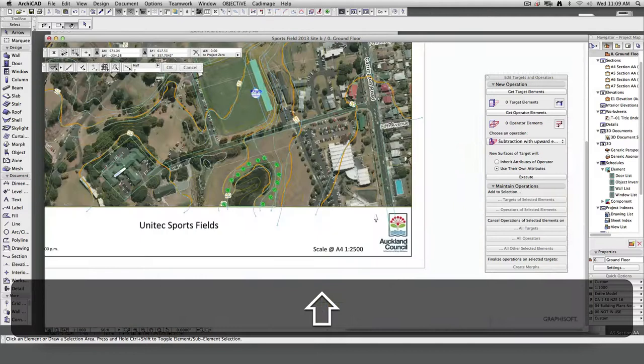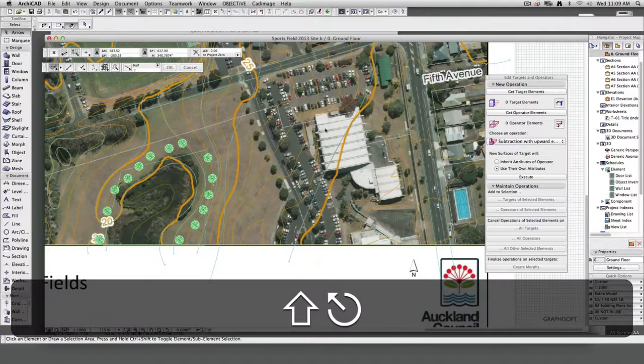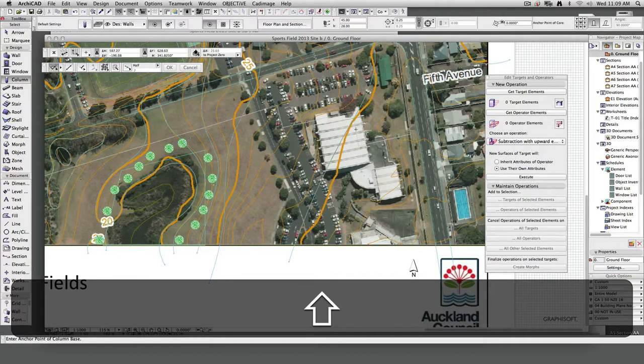Here's my gymnasium. First step is you've got to figure out what height that you're building at. In my case, I could read off the contours, but I've got rather crude contours. So I'm just going to grab the column tool with the gravity and I can hover around there. I can see over here that the Z is at about 28.2. Cool. 28. I don't get any lower than 28. So I'm going to set my walls at 28.